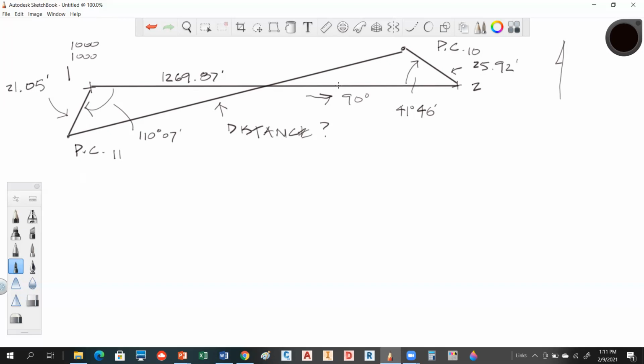Okay. Well, there's a couple of reasons. What was the reason of making this 1,000, 1,000? I wouldn't have to use 1,000, but what was my reasoning there? If it's 90-degree east, the other station would just add the distance to it for the east thing. Yeah, I agree with that. But why did I use 1,000, 1,000 for 1? Try to keep it in the positive coordinate. Correct. And I don't want to call that 1,000.662 or something. I want to keep it simple.